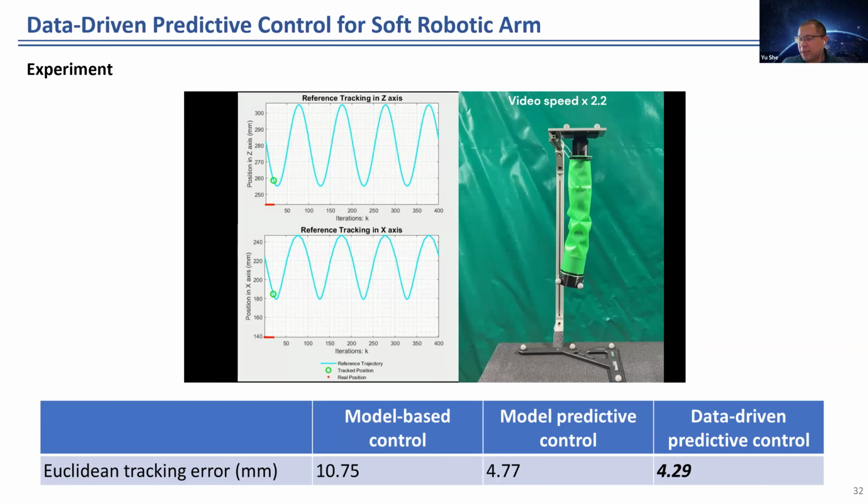Kind of a similar question a student asked previously: why not consider other form factors? Why prefer the suction cup? I get some of the information, for example, if we're using a gripper, you have additional inertia, like the payload from the motors, so that will create a kind of instability. But if we purely focus on the suction cup, will it create some potential limitations? For example, we may not have feedback from the suction cup, and every single time when you do the harvesting, can we ensure this is stably grasped? It won't fall, and we can detach from the stem.